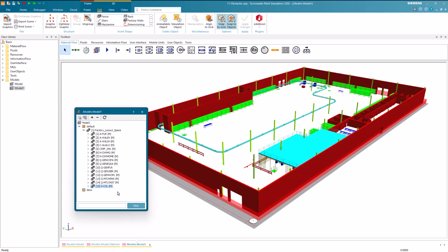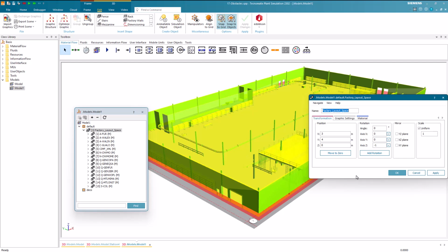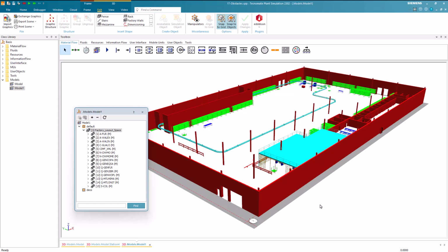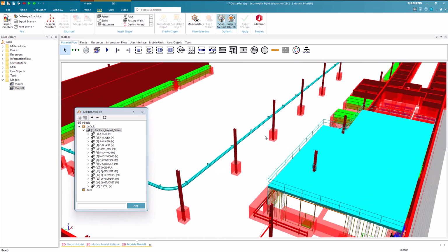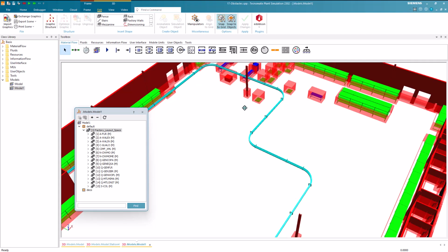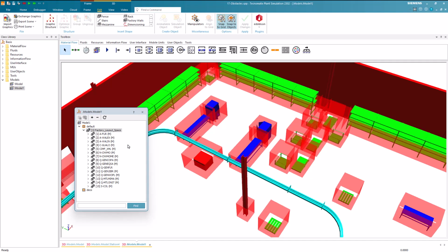As we've seen before, we can change this in the Edit 3D Properties of the Factory node. So we open them. Then we switch to the Graphic Settings tab and change the obstacle to Graphics and click OK. If we now close the dialog and show the obstacles again, we will see that each object is an obstacle. If you now have objects which shouldn't be an obstacle, you can go through the objects in the graphic dialog and set them individually as no obstacle.